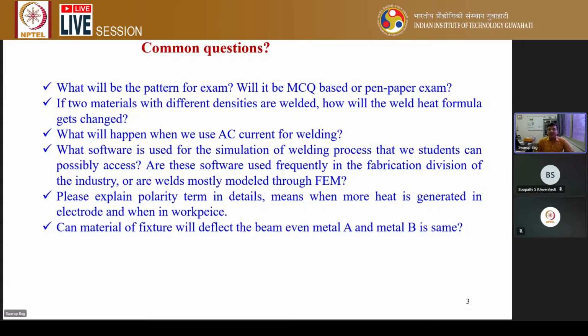But of course, it's a very simplified form. When the two different materials are mixing in the liquid phase and then solidify, the solidification behavior is completely different from other perspectives. When two liquid metals mix, they can form some different material. Therefore, averaging the properties of the two materials is the usual conventional approach to predict the properties and handle this kind of situation.